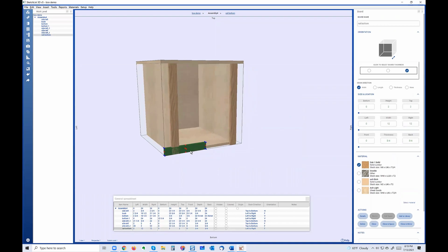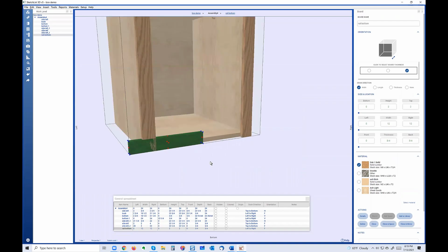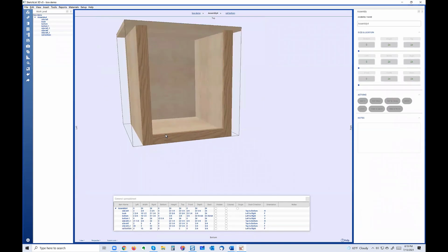Now, because there's a boundary, these two styles make the boundary. One of the shortcuts is if I hold down the Shift key, grab the red dot with my mouse and just slide it over, it will snap. If you saw it with just a last fraction of an inch, it snapped to the edge of that. So I can test that. The left of this is 20, the right of that is 20. I can do the same thing here. Just come here and then just hold down the Shift key, dragging the red dot, and we're all set.